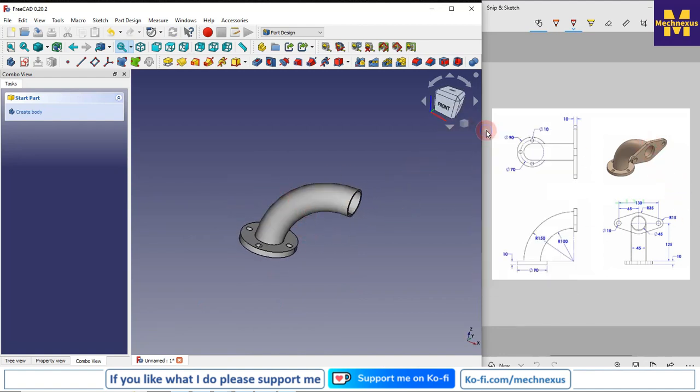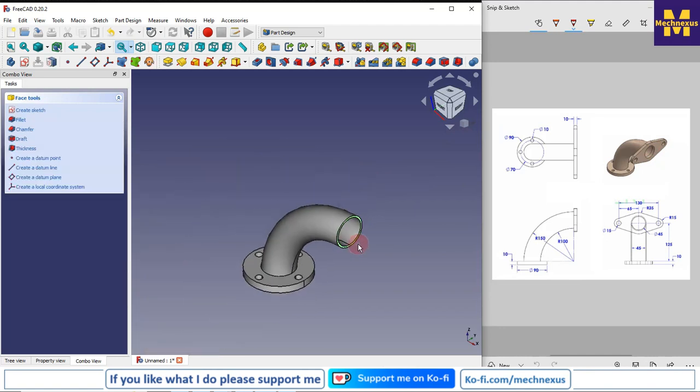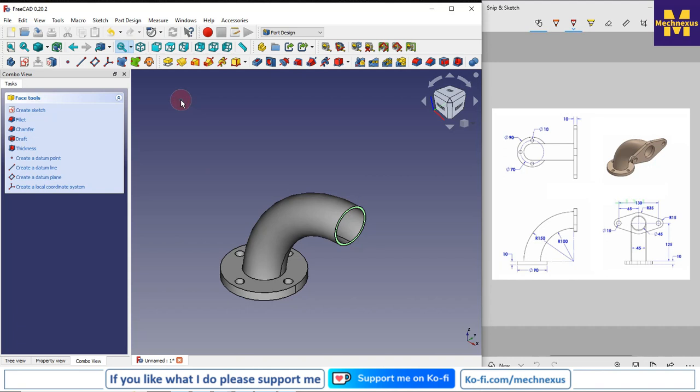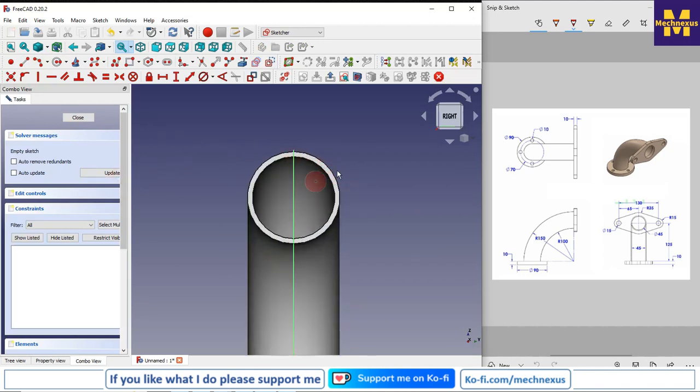So for this I will switch to the isometric and I will select this face, and I will create a sketch, and now I will project the outer edge. So I will select project geometry, and now we will draw this profile here.